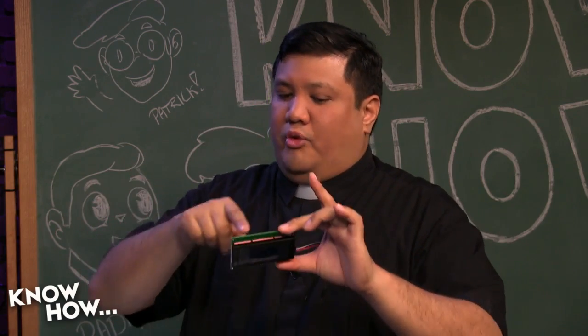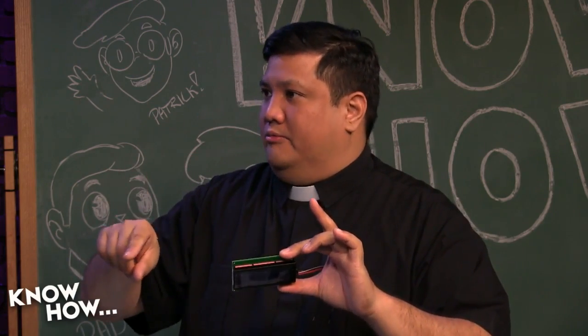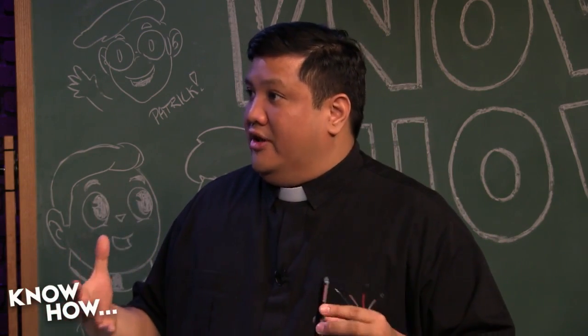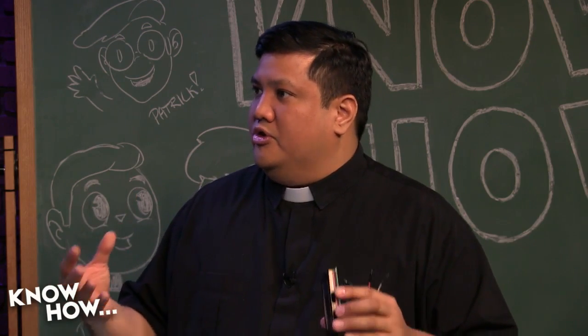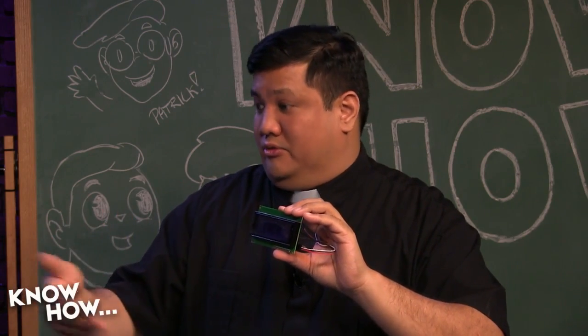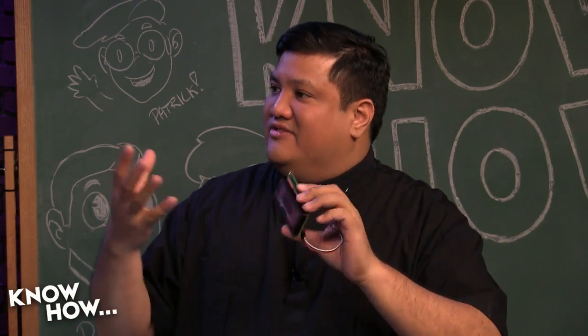Right. Well, that's because when it creates a pattern, be it a letter or a number or a picture, there's no light coming off of it. All it's doing is blocking light. So you need a backlight to shine through the liquid crystal, and then the light gets blocked or tinged in a particular color, as we do with, say, laptop screens, and that gives the final color that we see. You remember when I did that Game Boy project? I took apart the screen and put a backlight into it.